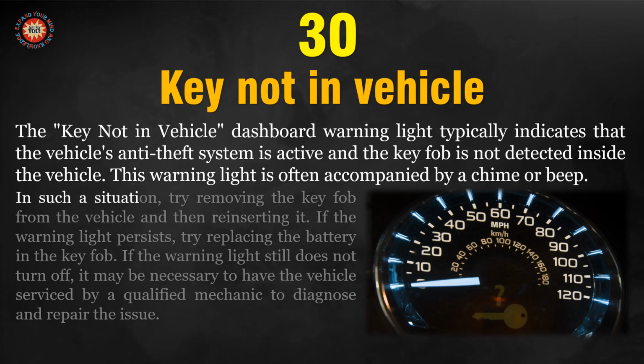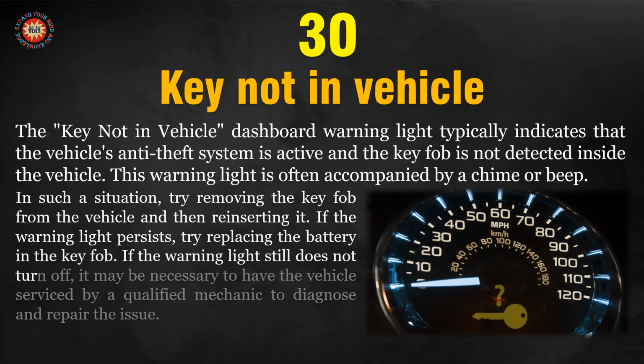In such a situation, try removing the key fob from the vehicle and then reinserting it. If the warning light persists, try replacing the battery in the key fob. If the warning light still does not turn off, it may be necessary to have the vehicle serviced by a qualified mechanic to diagnose and repair the issue.